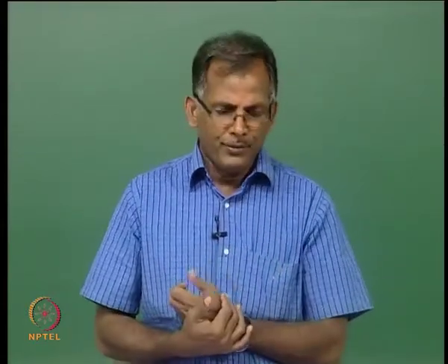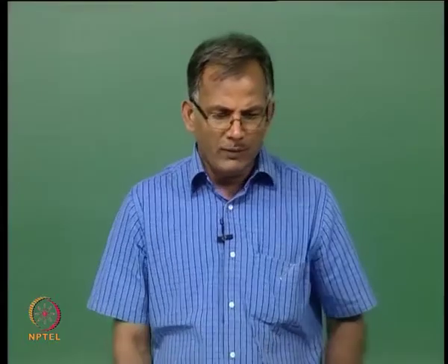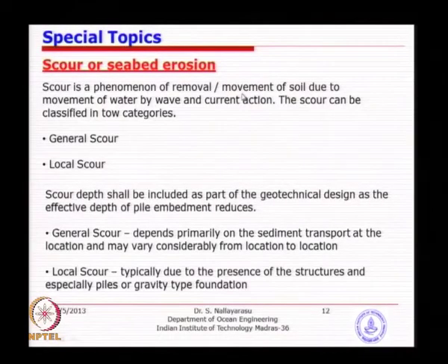But the problem is, if you put big boulders, the void space is still there, and soil may actually get carried away. So, you need to have an engineered fill, that means a graded fill, so that soil cannot escape. Normally we do this; scour protection means trying to avoid the particles going away. The scour phenomenon is very important, especially in coastal areas, because that is where you see a lot of turbulence, wave breaking, and also increased velocity because the energy is getting dissipated there only.